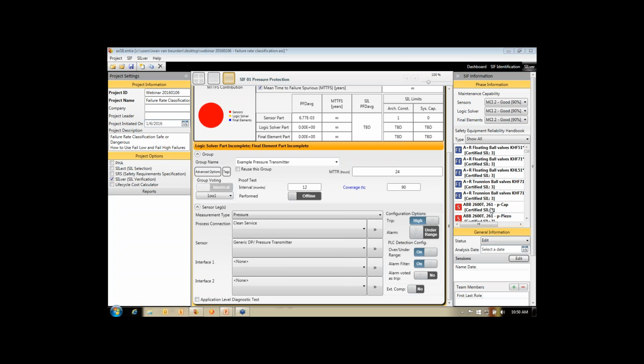It's not just the trip delay that you're implementing. You really need to be able to detect that that signal will end up in the out of range area. So if you implement a time delay, but you do not have the ability to detect that out of range signal, then it simply remains an undetected failure, and you will not be able to flag it as, hey, something is wrong with that transmitter.